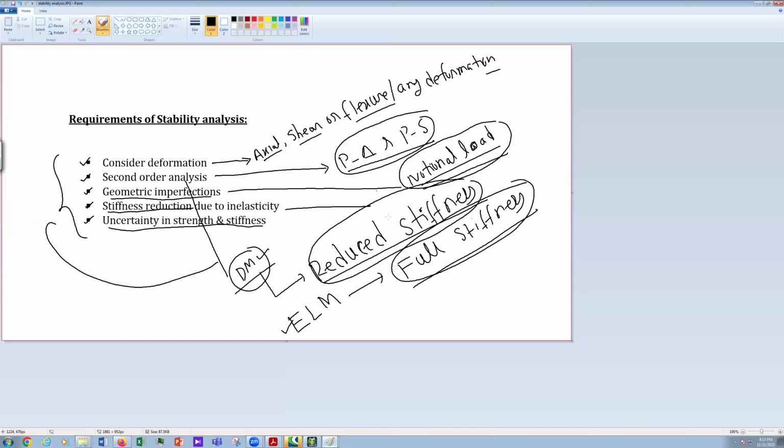Okay, another difference which is very critical, in case of the direct analysis method, if I go at the top, where is KL equal to L? That means KL equal to 1 into L equal to L. That means for the direct analysis method, K equal to 1.